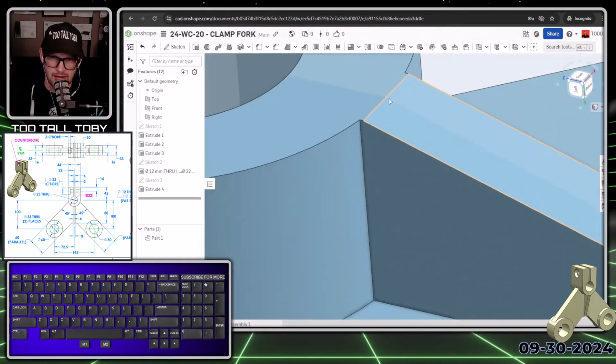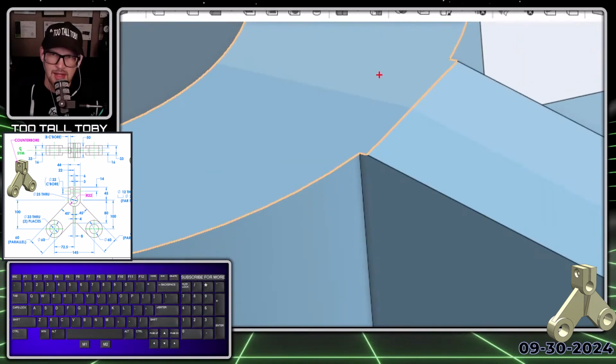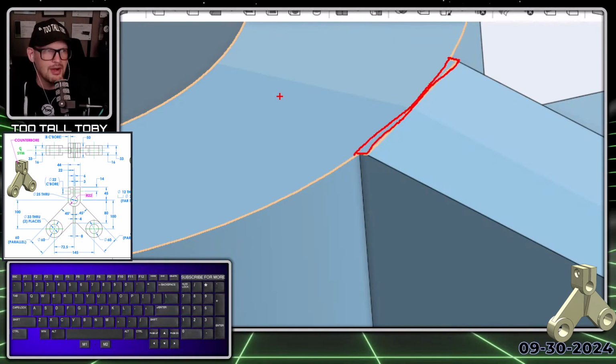Sometimes the customer will say, I want this to be exactly tangent, but the reality is it's tangent to where it originally was, but that means that we end up with this extra little, almost like a keyway sticking out here. And so depending on how extreme that is, depending on what the radius of the arc is compared to the thickness of the rib, the customer may or may not accept that as a solution. That's a discussion you got to have with the customer.